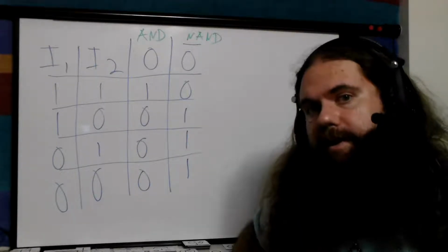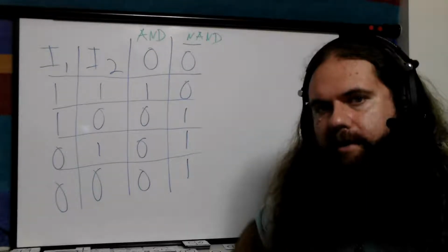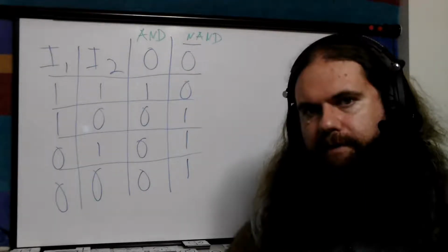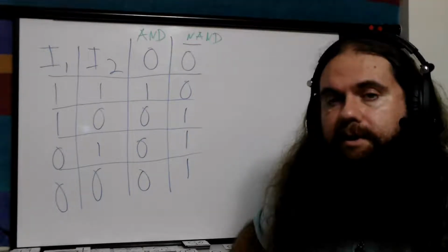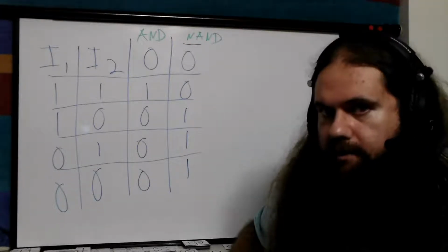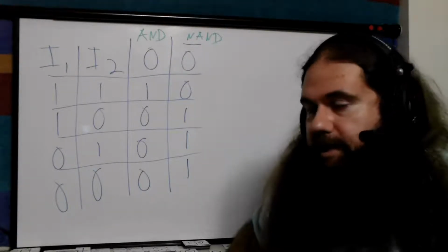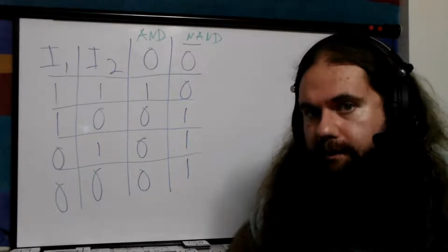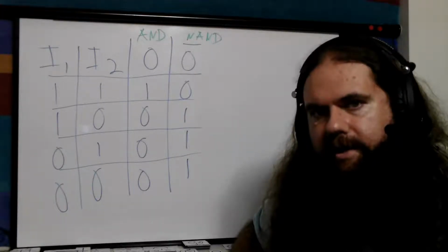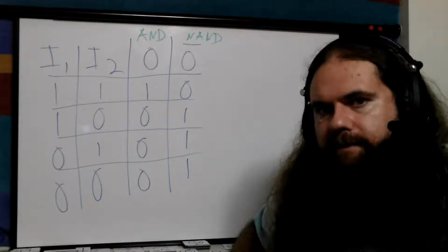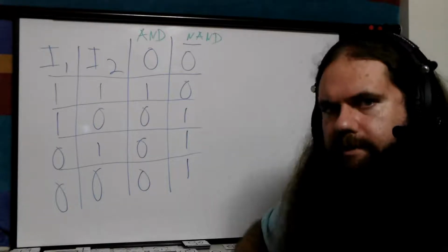You can do it with MOSFETs, but you can't do an AND gate with just BJTs because they have trickery involved. Because if you recall, and I'll show you the circuit, BJTs are actually 2 diode junctions, not 2 diodes, 2 diode junctions. And the way we have to wire them up to get the AND operation, if you use a MOSFET, it's perfectly fine. We'll get to MOSFETs in the future. But if you use a BJT, it actually activates one of those diode junctions where it shouldn't be, and you get a wrong value. So let's check it out.